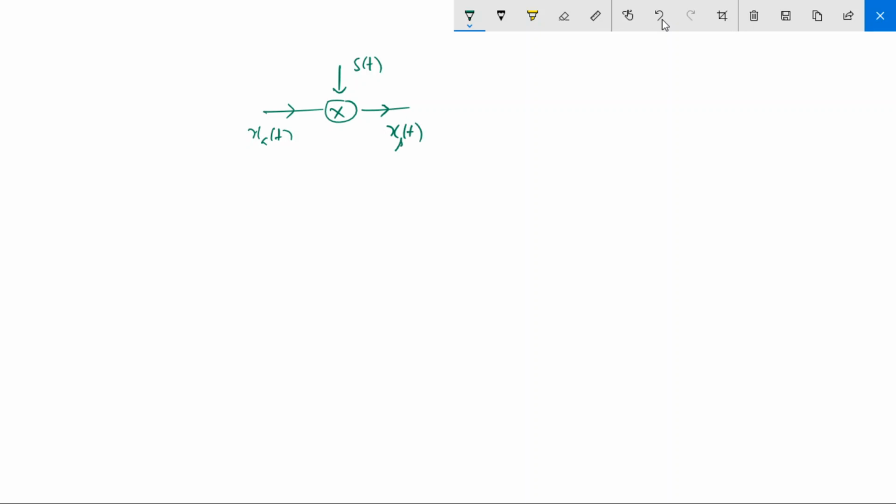The Fourier transform of this signal is nothing but the Fourier transform of the original signal shifted in frequency by the sampling rate. So you are getting replicas of the same spectrum. If you sample in time, you get repetition in frequency, and the frequency by which it is shifted is omega s, and this was omega n, minus omega n.